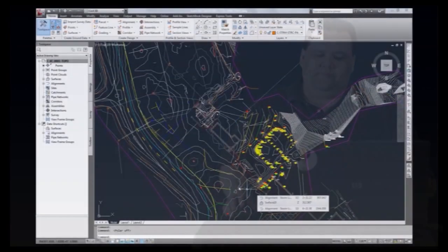Our second tip is for Civil 3D users. Whether you're working with external references, data references, or drawing specific information, keeping things in order is very important. Thankfully, Civil 3D provides us with plenty of opportunities for internal documentation. At the very least, you should take the time to name and identify your AEC objects. Doing so is going to make working with your projects much easier for you and others in the future.